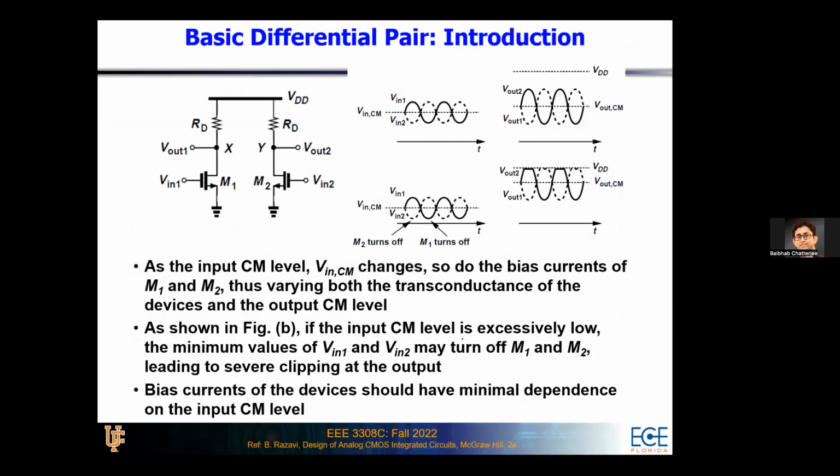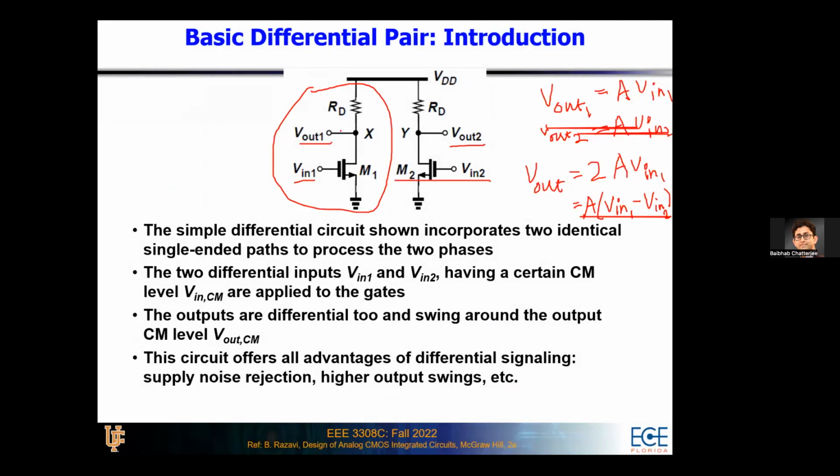Now, yes, question. Yeah, so your output is right now here. It's 2 points. Vout1 is output, Vout2 is also output. You're considering the difference of those two outputs as your final output. So you always measure voltage between 2 points in your circuit, right? What are those 2 points? Usually it is Vout1 and ground, or Vout2 and ground. Now instead of putting the positive terminal of your oscilloscope to Vout1 and negative terminal to ground, you'll put your positive terminal to Vout1 and negative terminal to Vout2. And in that case, you'll see double of the swing that you see in either of those cases.